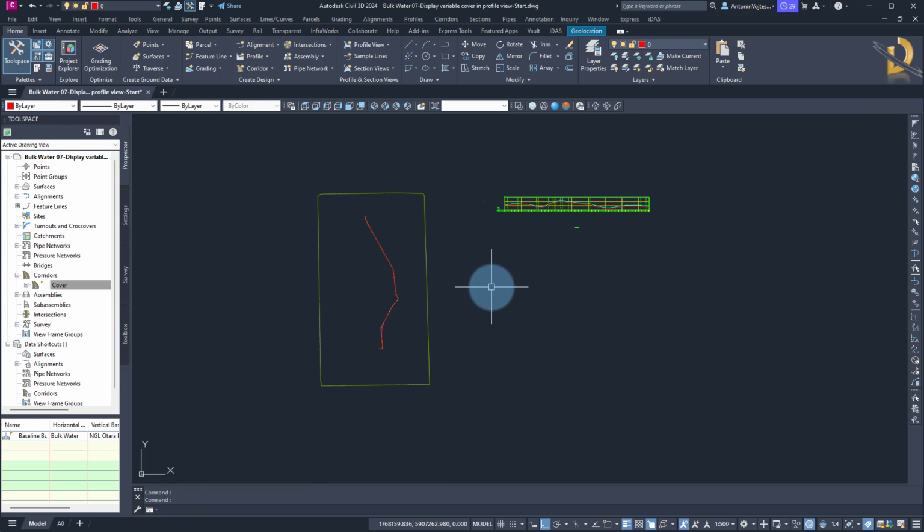You may also consider in your project that you create your corridor in a separate drawing and you can reference it into your destination corridor. I didn't test whether you can extract dynamic feature line from the reference corridor, but I believe it should be possible. So you should be able to do that to keep your design drawing as light as possible.